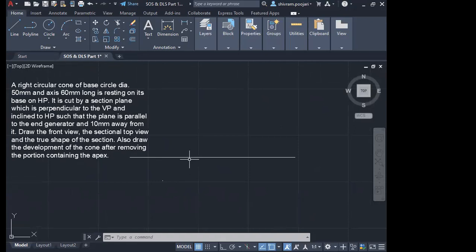So you can draw it by taking a distance from the top. You can take a distance of 90 mm. 90 नहीं, एक काम करो, डबल ले लो, 120 mm ले लो. From the top, you take 120 mm distance, and then draw the horizontal line. Everyone, draw the horizontal line, 120 mm from the top.